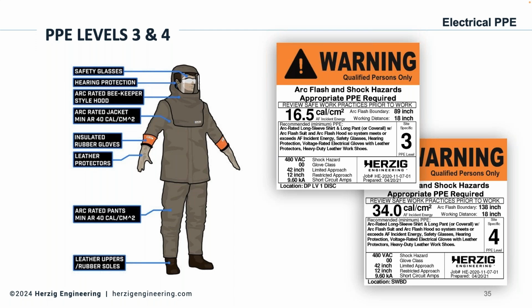It is important to note that in the 2024 version of the 70E, leather protectors are not the only kind of protector gloves that are available now. They do make arc rated ones. The vast majority of people still just have leather protectors though. But if you're already upgrading and getting the fancier newfangled arc rated protector gloves that have been approved to put over rubber gloves, fantastic, good for you. That is absolutely acceptable as well. 2024 just says protector gloves. So we're making the point there.